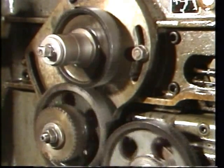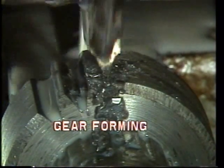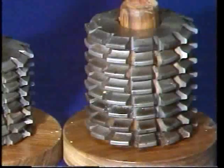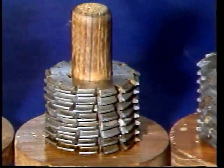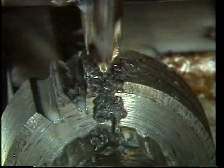To transmit high torque at greater speed with accuracy, gears made by metal removing process is preferred. In form milling process, the cutter has a profile similar to the form of the tooth space. The tooth space is a copy of the cutter. A wide range of cutters is required for gears of different number of teeth with different base circles. Hence, in practice, each module range includes a set of 8 standard cutters, producing an average result which is a fair approximation to the ideal.